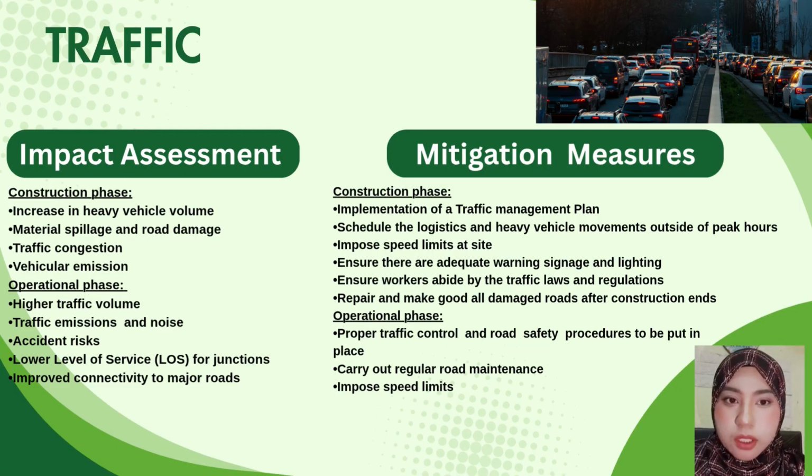Impact assessment for traffic. Construction phase: increase in heavy vehicle volume, material spillage and road damage, traffic congestion, vehicular emissions. Operational phase: higher traffic volume, traffic emissions and noise, accident risk, lower level of service for junctions, improved connectivity to major roads. And the mitigation measures for traffic.